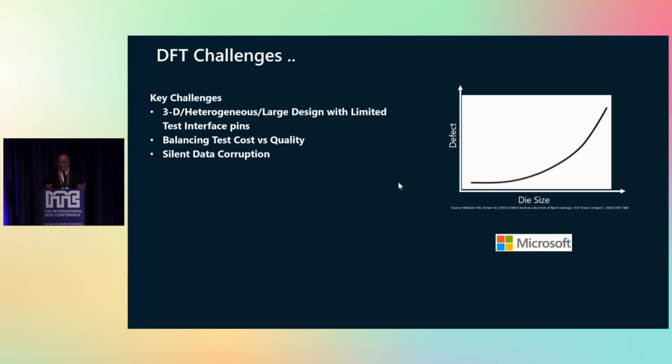And you still have to get your DFT done at the required quality. And then the sizes of these chips are growing inside a package. What used to be a quality requirement for a chip now becomes the quality requirement for this entire 3D IC and the package. And as you can see from the William Brown model, as the chip size goes up, defects are going to go up, and we need to come up with much smarter and scalable DFT methods to cover these